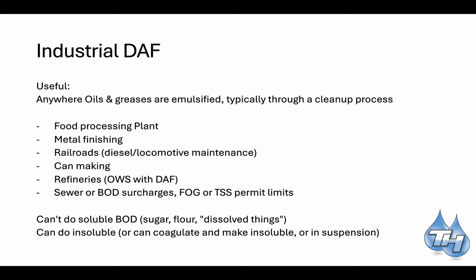DAFs can't do soluble, things like sugar, flour, things that are dissolved in water. If it's emulsified, that is doable. But if it's soluble, that's a different story. We would typically look for more of a biological process. Something that we can help with just wouldn't be a DAF system, most likely. So we can do insoluble, or we can coagulate or make insoluble in suspension.